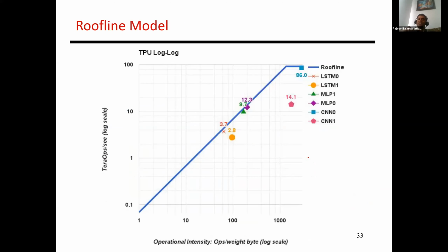Okay, all right, maybe I'll explain that a little bit more before I move on. Let's talk about this curve, since I'm talking about fetching of weights. This is referred to as a Roofline model, which helps us understand the performance of the Google TPU. On the x-axis, you have the operations per byte being fetched, right? For a fully connected layer, it's going to be right here. It's going to have one operation for every weight that I fetch.